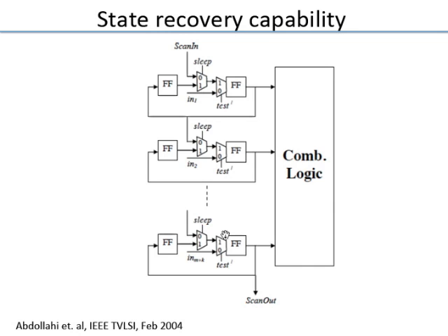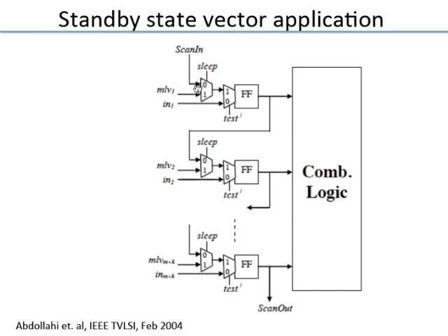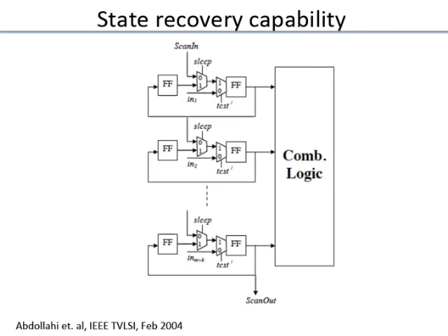in through the scan chain all the time, which is not good because it will take a long time to get into standby state. So if you see, this figure by itself has to be modified for a complete implementation. So maybe this has to be a 3 input mux like before. Maybe you have a 3 input mux where the standby state vector is hard coded and that comes. Because if you try to scan in the standby state vector, it will just take a long time.